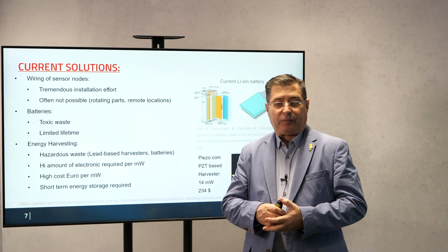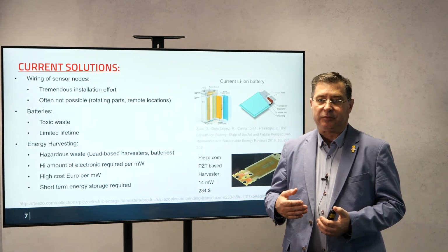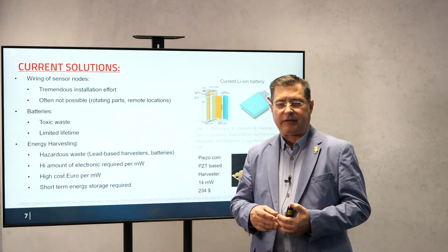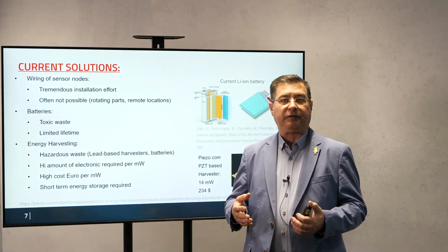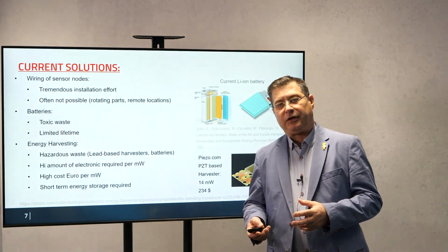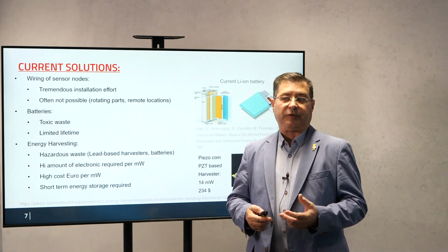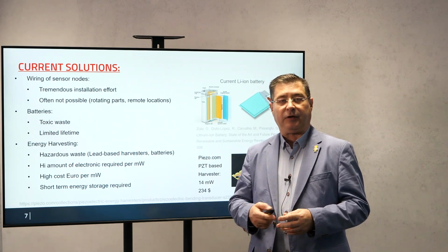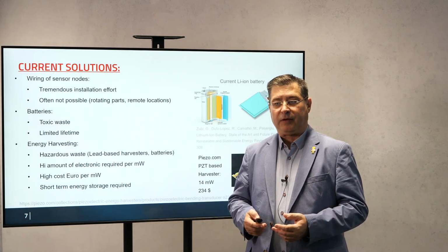The first important thing when you're doing piezo harvesting, the current solution using a piezo harvester and a battery, is that the piezo harvester is not something from the shelf. You have to find the right manufacturer who can make this piezo harvester for you. Also, for storage it is not always good to use only a lithium-ion rechargeable battery. Sometimes it is a different possibility to use supercaps or capacitor banks. It depends on how often you have this energy flow.